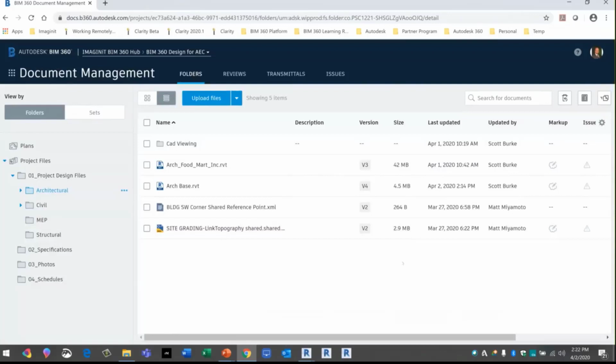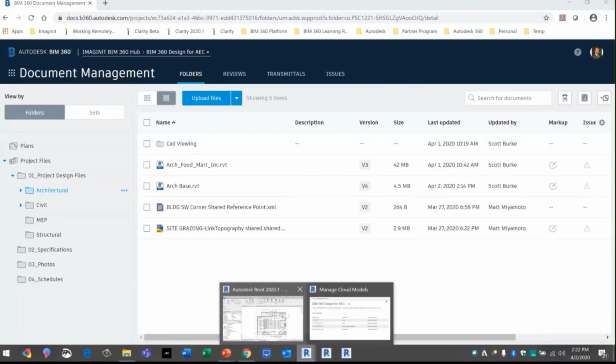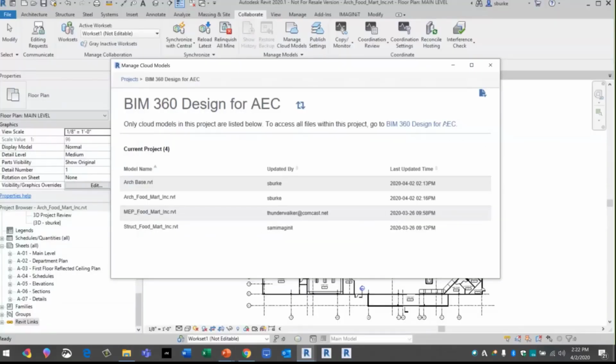Now let's say whatever you're working in Revit, and it happens, right? And the model, you can't save to it, it gets corrupted, right? Halfway through a save, the power went out, internet went down. Things happen, or more commonly, the number one cause of corruption is someone opened the same version of Revit, but a different build number than the rest of the team, and it messed the model up. Okay, so again, as long as everyone's saving every 30 minutes, this is good.